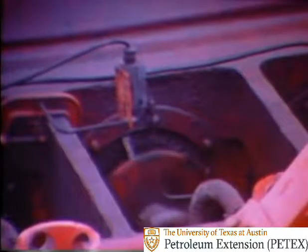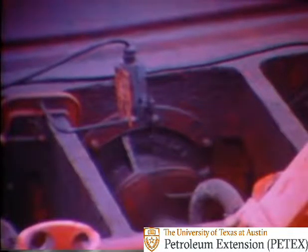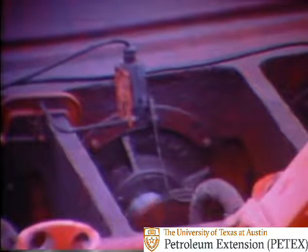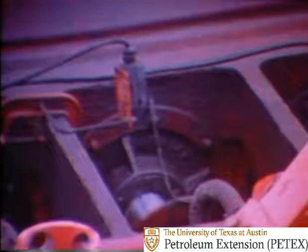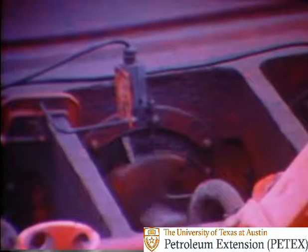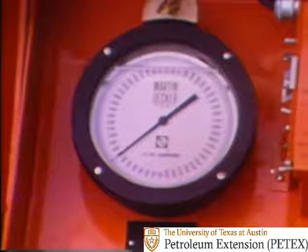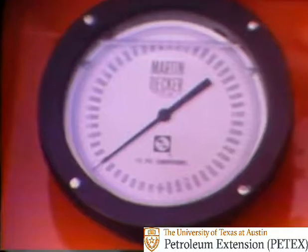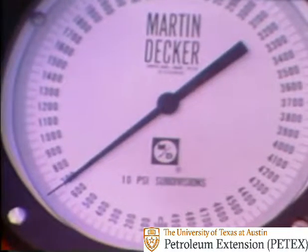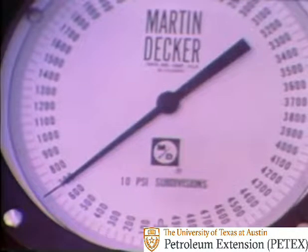It is desirable in any well control method to run the pump at reduced speed when circulating out a kick, to avoid excessive circulating pressures that could develop and exceed the pressure limitation of the pump or cause exposed formations to break down. At least once each day, the pump should be run at reduced speed, and the speed and circulating pressure written down for reference in case a kick develops. The pressure obtained from such a test procedure will be referred to hereafter as the pre-selected reduced circulating pressure.